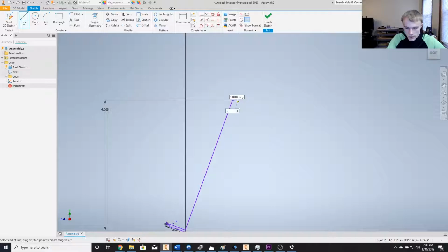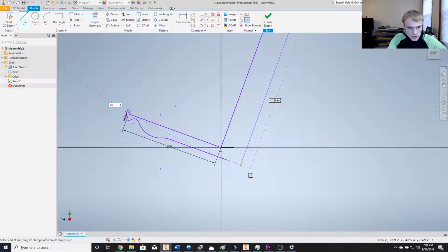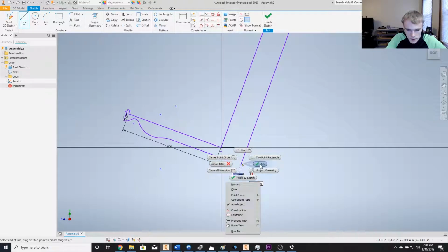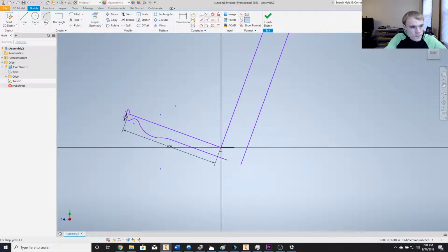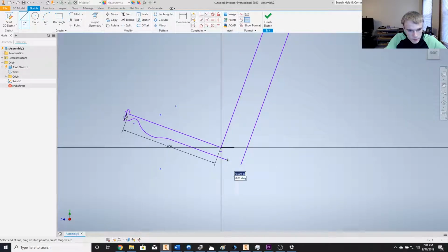We're going to make this 0.15 inches. 90. Lock it in at 90. And then we just change the length. Perfect. Just like that. Oh, wait. That's not exactly what I was looking for. Oh, you know what? We'll round that out with a fillet too. Perfect. Yeah, that'll work. So we're going to bring this line back to here, and we're going to close that sketch out.